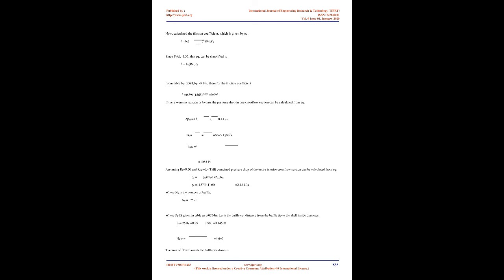7.2.5 Channel covers. The channel covers are round plates that bolt to the channel flanges and can be removed for tube inspection without disturbing the tube side piping. In smaller heat exchangers, bonnets with flanged nozzles or threaded connections for the tube side piping are often used instead of channels and channel covers.